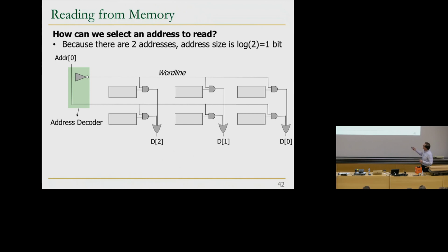Okay, let's take a look at this one. You've seen this also before, and this is called a multiplexer. It's a mux. What it's doing over here is really selecting. Remember, a mux is a selector, multiplexer. It's selecting between this register and this register. And we've seen exactly this circuitry in an earlier slide, in the last lecture. If the address is 0, it's selecting this value to go out. If the address is 1, it's selecting this value to go out.